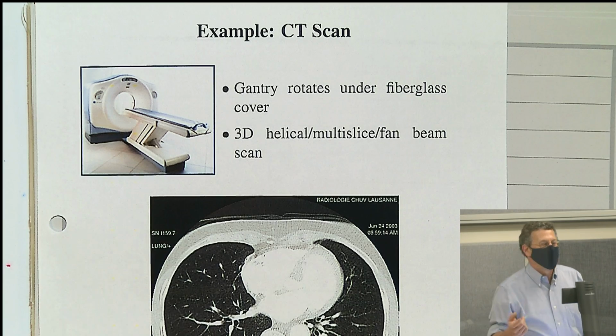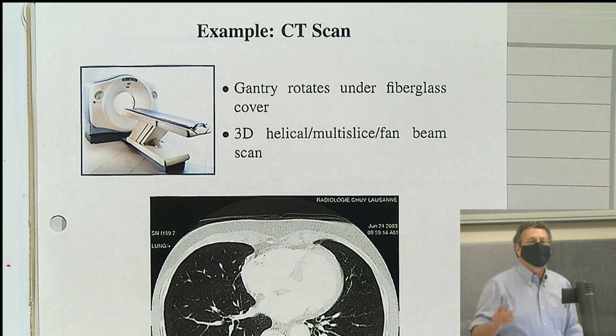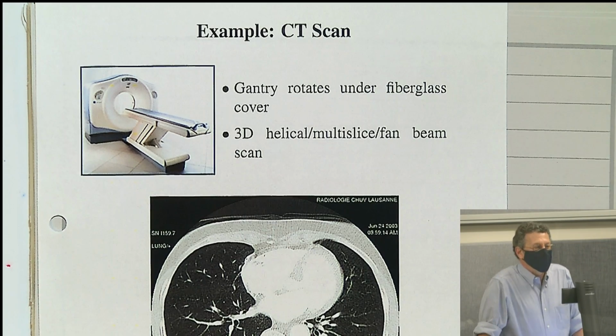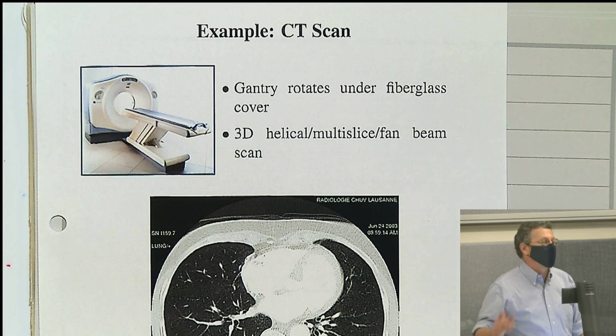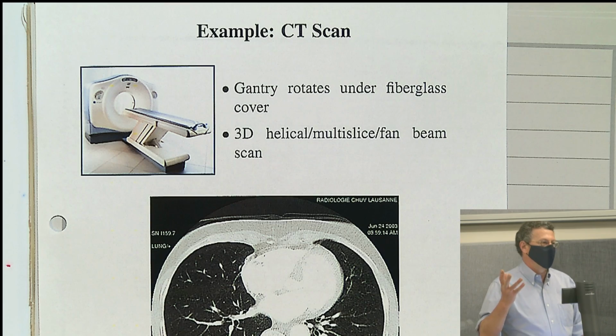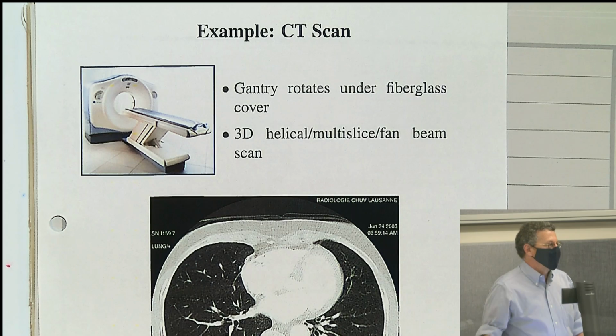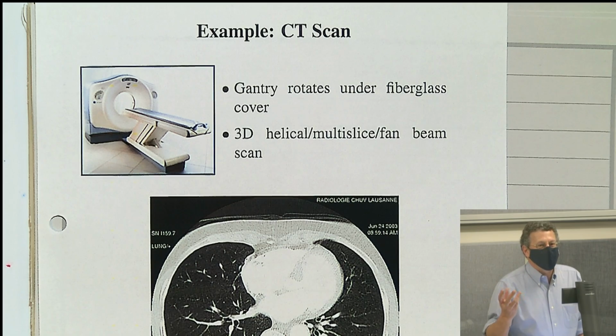turbine blades. Because if you have taken a thermodynamics course, which you should, you'll find that the efficiency of an engine is related directly to the combustion temperature. So higher combustion temperature, higher efficiency. But if the combustion temperature is too high, you melt the engine. So those blades are made out of things called superalloys, which are like single crystals of metal that are designed to actually get stronger as they get hot.